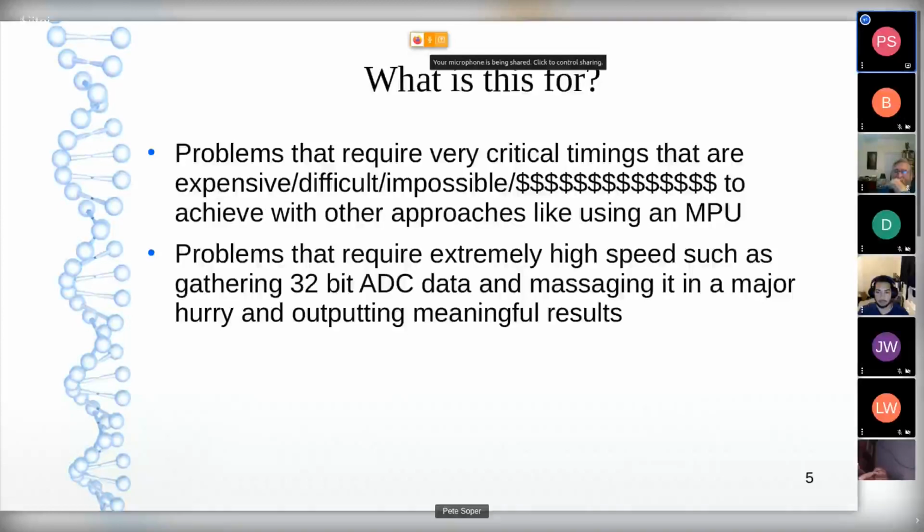Like, say, sensing a state change on a pin and doing some really clever stuff like, say, multiplies and math and other stuff, and being able to somehow respond on another pin very, very quickly. And so quickly handle timing relationships. In fact, using purely combinatorial logic, the latency could be as little as maybe 10 or 20 nanoseconds for the chip that we've been looking at.